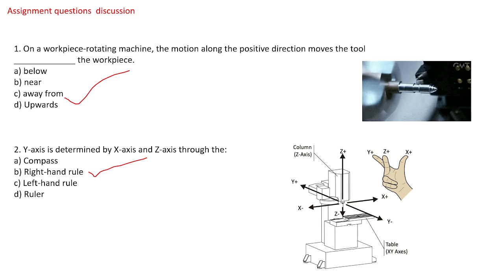Future will be more on nano machining, because now we are talking about only microns, 10 micron. Generally I'll always say that CNC machines can produce 10 microns and above. Only when you use a jig boring machine, 5 micron and above. Then when you use a grinding machine, you will come closer to less than 5 microns. But as we are seeing now, the new era will be nano machining.